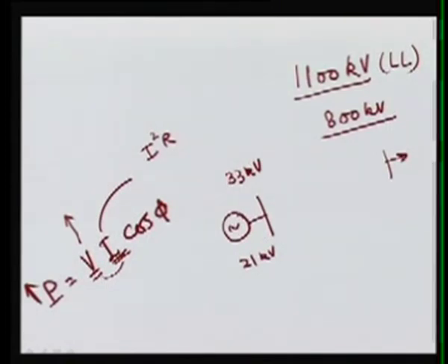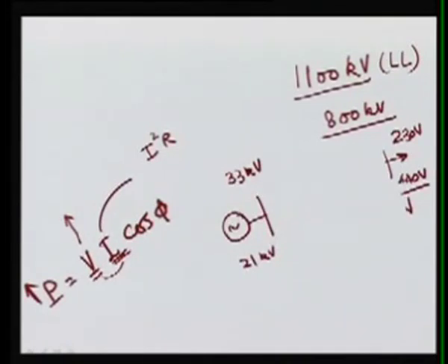So this customer, mostly the customers use 230 volt single phase, or it may be 440 volt 3 phase. Some large customers also utilize power at 11 kV, some customers utilize 25 kV, railway utilizes 25 kV, and also some customers like the Power Fertilizer Corporation of India use power at 132 kV, they take it, and then they utilize at the various levels. So we know that we are utilizing power at low voltage.